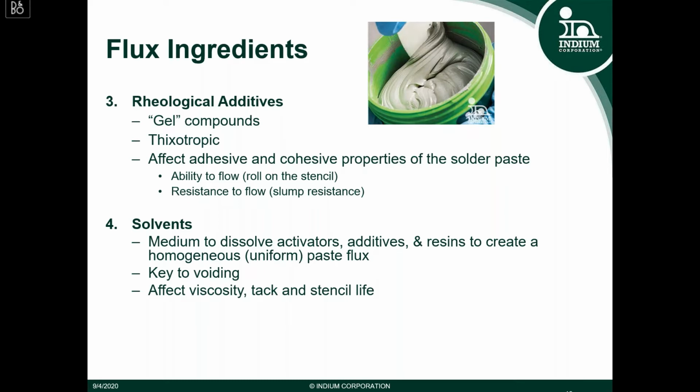The solvents are chemicals that homogenize the flux. They dissolve the activators and rheological additives and rosins, and they make a uniform paste mixture. The solvents are key in voiding, and they do affect the viscosity, tack life, and shelf life of the flux.